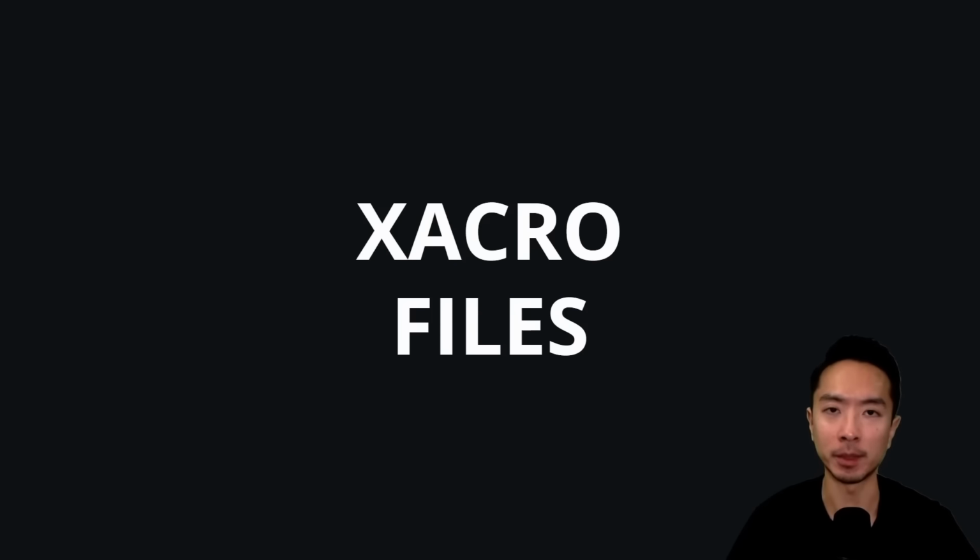So now I want to talk about Xacro files. We just finished talking about URDF files, but what are Xacro files? You could think of Xacro files as files that allow you to create functions that you can call inside your URDF file. The main idea behind this is you don't want to have a lot of repeated code. This will help simplify things and make your URDF much more readable. Let's go ahead and see how this looks in VS Code.